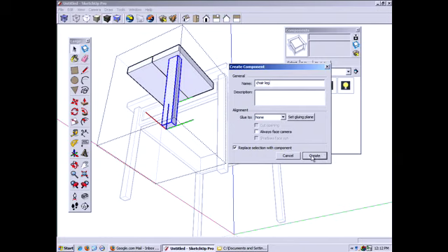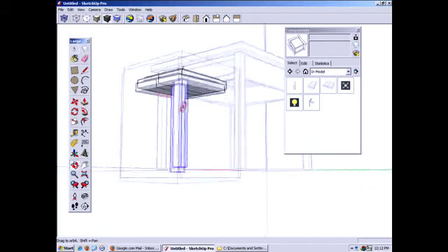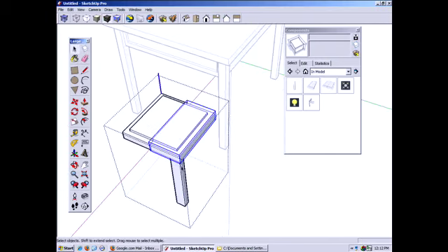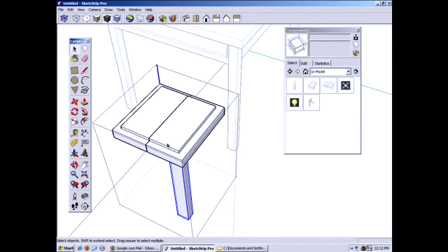Chair leg, create that. Now I've got a number of different components all inside this larger component. Wouldn't it be easier when you draw the box to make it a component right away, and then edit this? That's also a good way. The suggestion was when you draw the first box, make it a component right away. Absolutely. It's your preference.